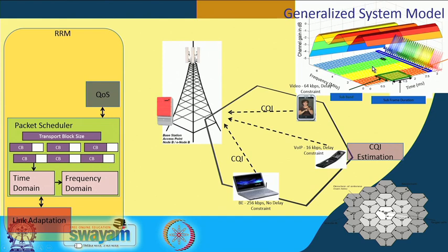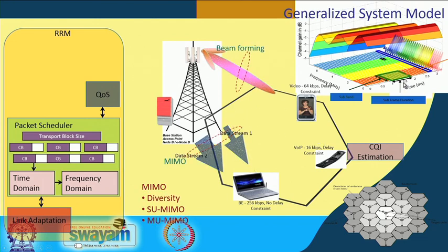By time domain scheduling, what is meant is the packets are differentiated in time domain, so that different requirements can be met for different users, and by frequency domain it takes advantage of the fluctuations along the frequency axis, so as to allocate the appropriate resource block to the appropriate user.